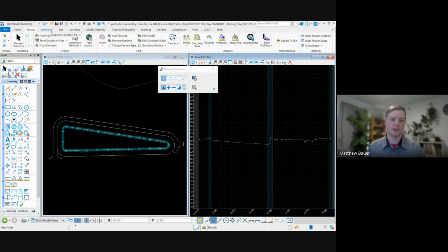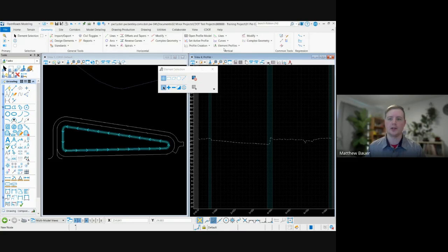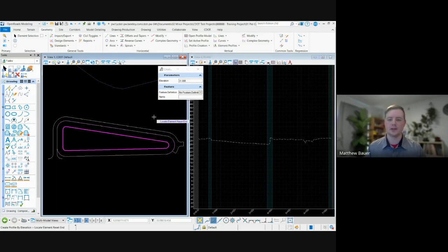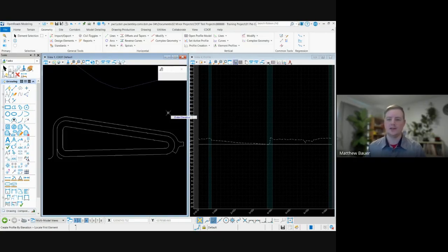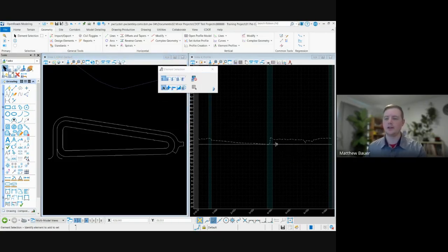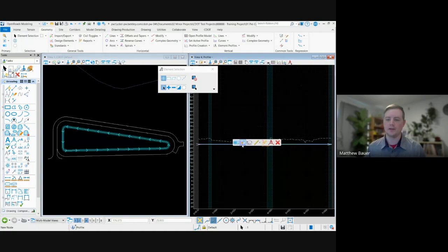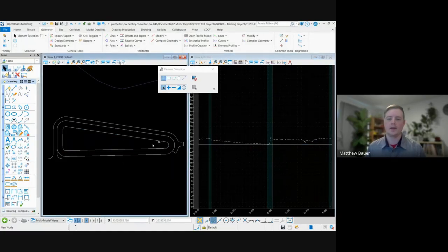some elevation data. So I'll switch to the geometry tab here. We'll do profile by constant elevation. This is just the bottom of a pond. So usually if you're doing this, the elevation is already defined. I want this element, and we'll do it at 26. So now I have a line drawn in here. This is the 3D element. It should be set active. We'll set it active.